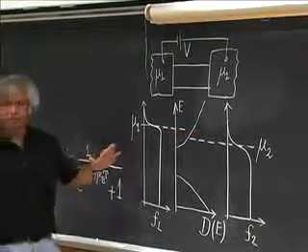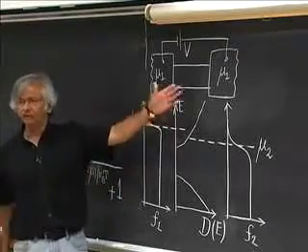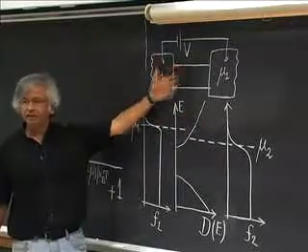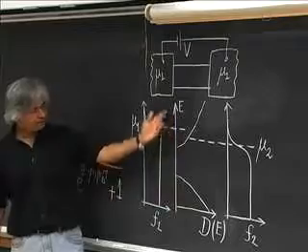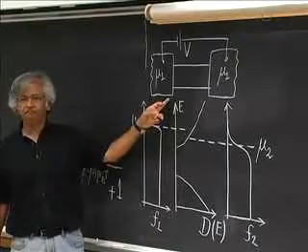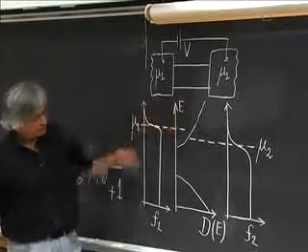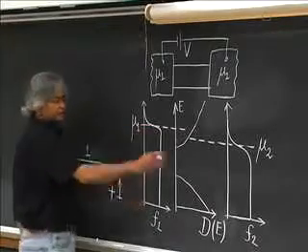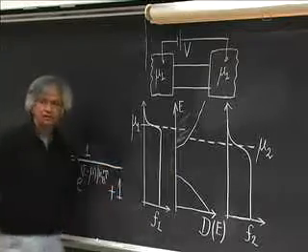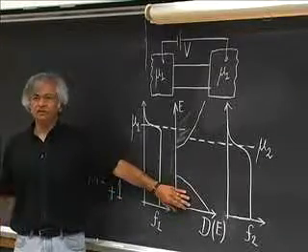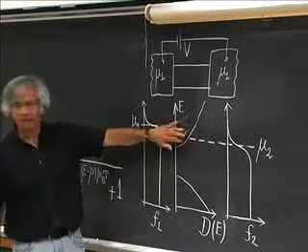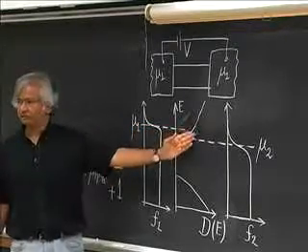And one of the first things, as you know, you should do is try to draw what you might call an energy level diagram, something that tells you where the allowed energy levels are inside this channel. And what I've sketched here is some general density of states, this D of E. So this axis is energy, and it tells you the density of states, and I've sketched some generic density of states. So typically you have some non-zero value up to here, then you might have a band gap of sorts, and then you would have some density of states down here again. Okay. And current flows if there is a density of states available around the chemical potential.